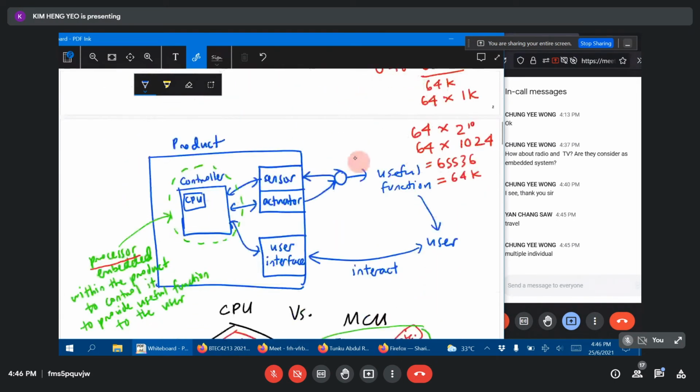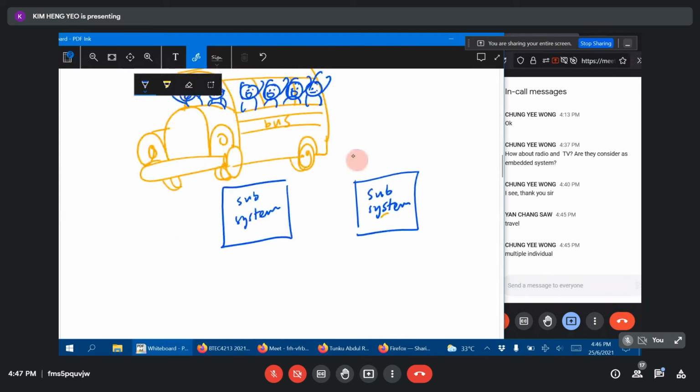Buses are just a collection of wires for data exchange between subsystems. Any complex digital system will have a lot of blocks. Each of these blocks performs some specific operation, and they all need to exchange information. The information is not just one wire, it is a collection of wires. This collection of wires carries data and clock signals. They are all related. So we call this set of wires a bus.